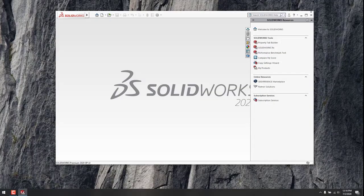One thing to consider if you've already got SOLIDWORKS installed is whether or not you need to transfer your old license. Unless we want both the old license and the new license to be consumed by this same computer, we would first want to release that old license. That may be because you're upgrading, or it may be an old license type that you want to leave available for another computer somewhere else.